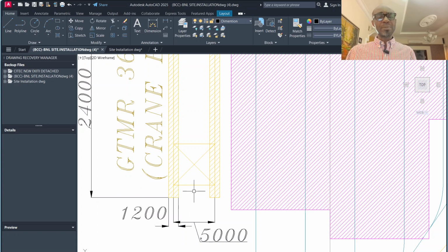The depth will be determined by the nature of the soil that this is going to rest on. If the soil is very hard, sometimes the thickness of the beam will be maybe 400 or 500 millimeters thick. But if it is in a swampy area, it can go as high as 800 millimeters to 1 meter.